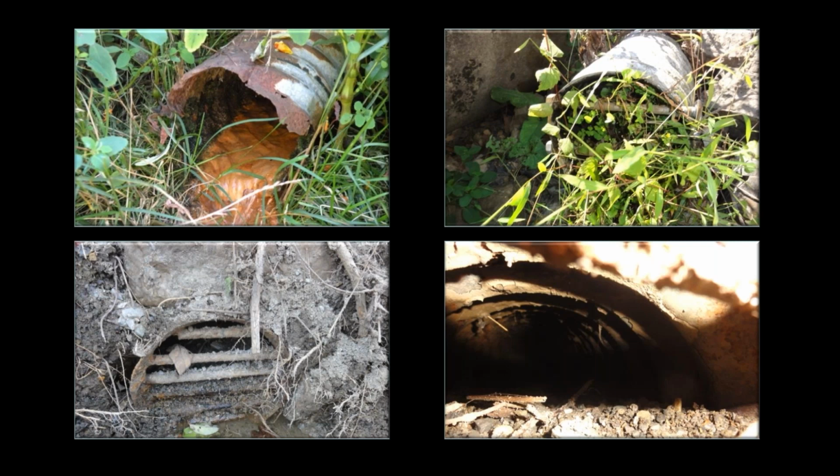So that as the groundwater or the seepage is collected and filtered, when it finds its way into the drain pipe, which is normally perforated, it responds to the oxygen and you can get a precipitate. And in some cases, that precipitate can clog the pipe. So on a modern dam, you will have a clean out at the upstream end of the pipe, so you could flush it out periodically as well as do a camera inspection.